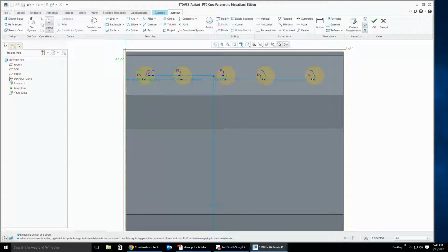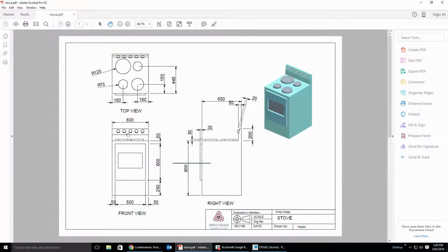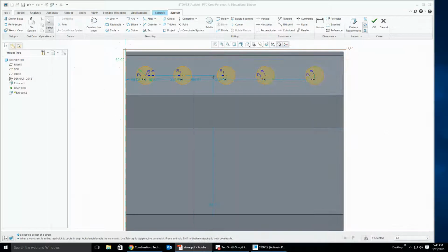If we look at our drawing originally, we know there's 5 of them. We'll try and space them out as even as we can. So looking across the screen here, we can see they're all bunched. They're even here. There's a larger gap on the side. So that means we have 1, 2, 3, 4 larger gaps and then 2 on the end. Our width is 600. So we have 4 in the middle. And we've got 600 and our diameter is 50. We know that 1, 2, 3, 4, 5 has a total of 250, less our 600 leaves us with 350.